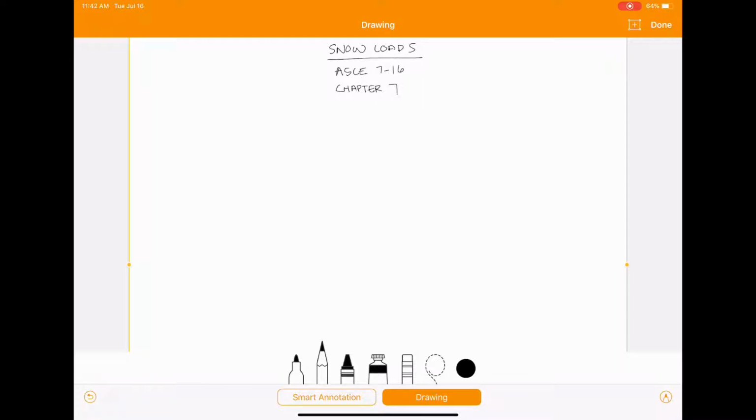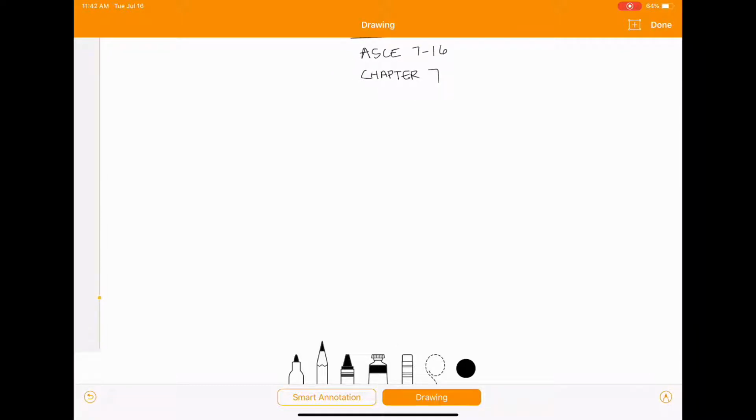So the first thing you want to do when trying to find your snow loads is find your ground snow load, which is abbreviated as PG. So that's your ground snow load. And the first place you're going to look to find that is going to be in figure 7.2-1. And in this figure, it's a map with values of the ground snow loads in different locations.